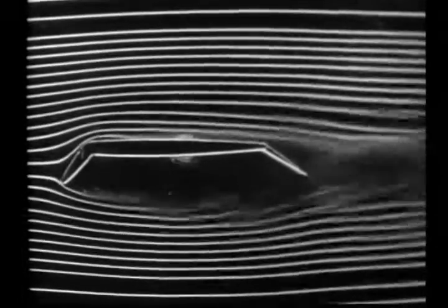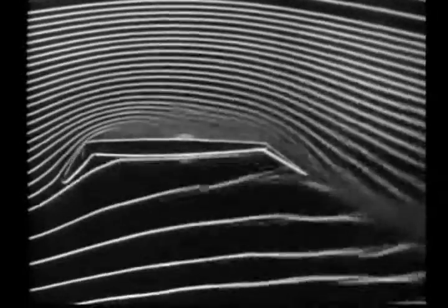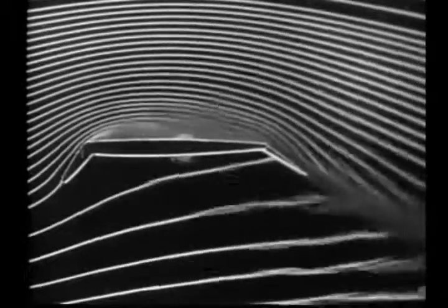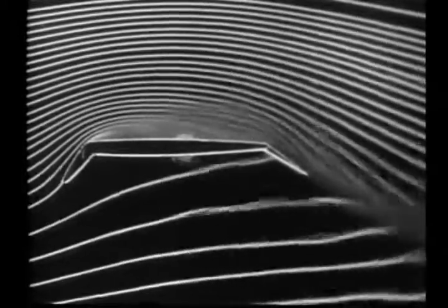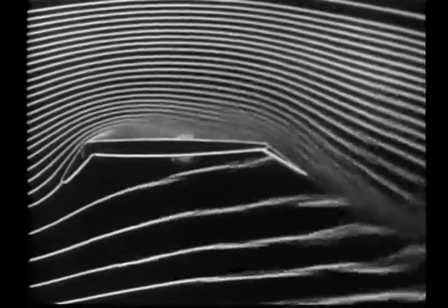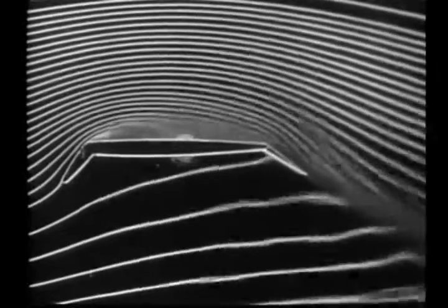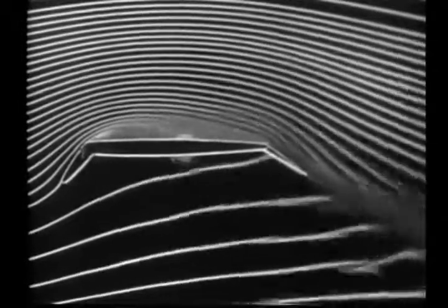Both the leading edge and the trailing edge flap of this thin profile are deflected. Because of severe pressure gradients, the flow is separating from the lower surface of the leading edge, from the break of the leading edge flap, and from the break of the trailing edge flap. By blowing air over the trailing edge flap, the separation in this region is suppressed and circulation of the profile increased. This increase in circulation so alters the flow field that the adverse gradient at the leading edge vanishes, and separation at that point is also suppressed.